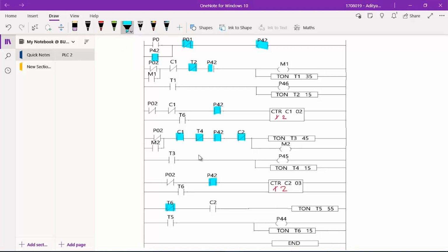Now if we put the third object on the conveyor belt, like before, it will get sensed by the sensor P2 and it will make all the P2 across the ladder logic diagram active. Whenever this P2 is active, the counter will count to 3. As the initial set count is also set as 3, this C2 will become activated.